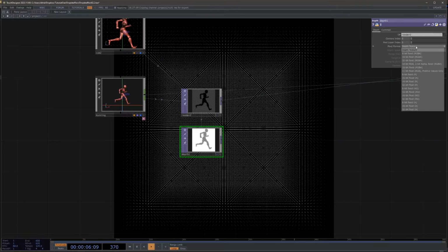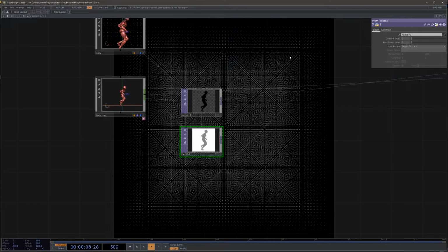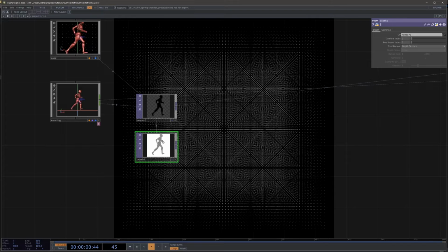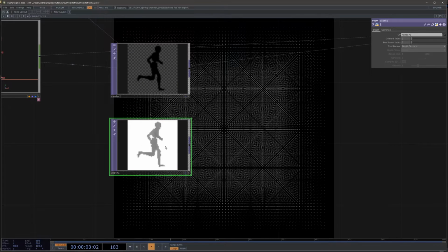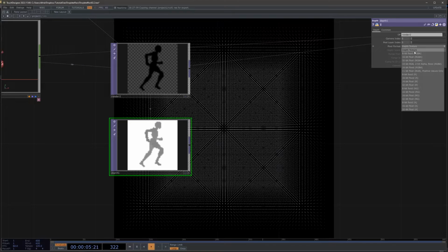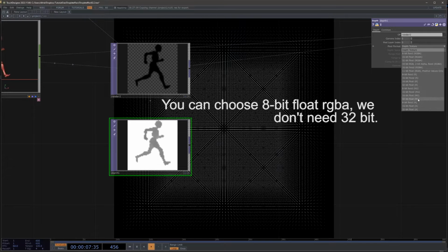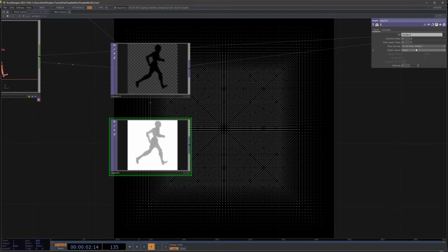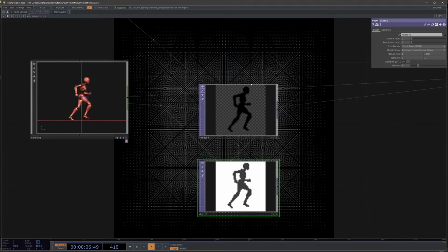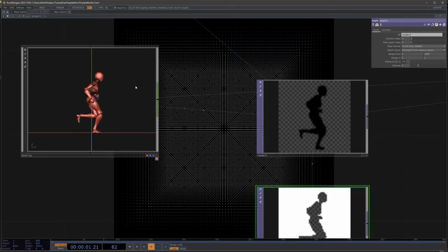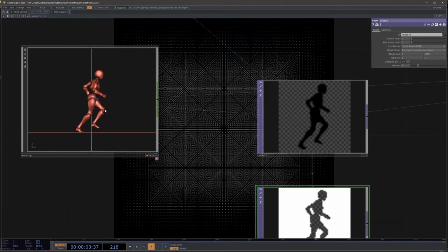It could be doable, but because I want to have more control over it, I'm going to use 32-bit float RGBA and remap from camera space. And so the range we want is 0. And because our camera is 0.23 offset on the axis, I'm going to put 0.23.